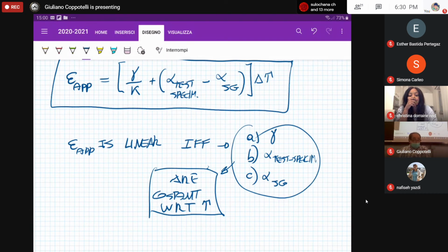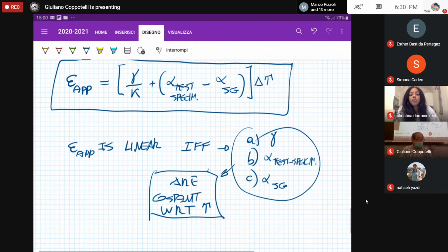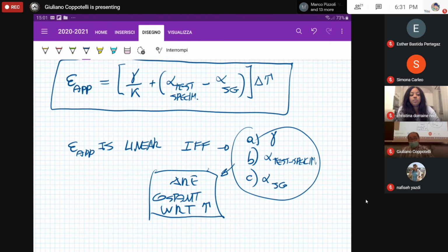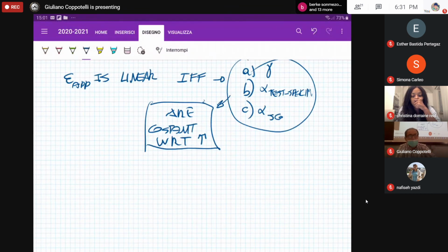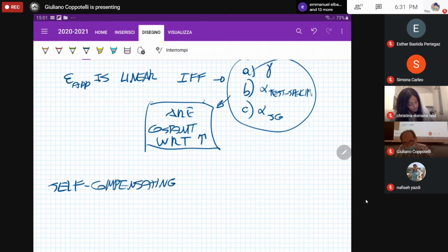What is generally done from the manufacturer point of view is giving you a third option in order to take into account this thermal effect. And this third option is what they like to call self-compensating strain gauges with respect to temperature. They like this phrase a lot for this type of strain gauges. So the self-compensating strain gauges